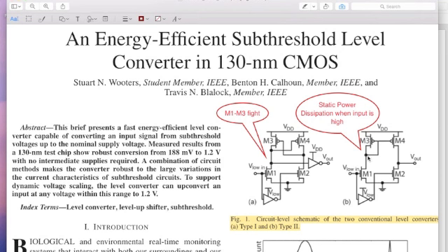So this is not as turned on as this, still just in the near threshold region, and so this structure is able to work properly even when the input voltage is close to subthreshold. But the problem is when the input is high, M1 is on, the output comes down, but it doesn't go all the way to ground because of this diode connected PMOS.